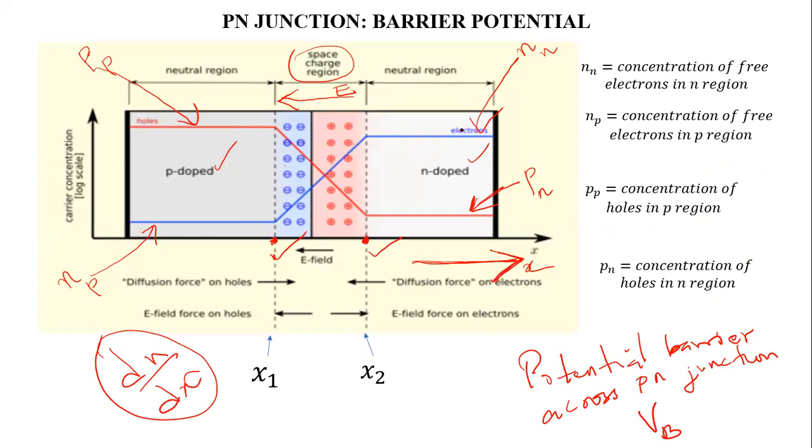The diffusion of electrons has to go from this to this direction, as you see. But if you put an electron here, under the action of this electric field, since this side has negative ions and this side has positive ions, electrons will tend to move in this direction. So the diffusion current direction and the drift current direction across the p-n junction will be opposite.